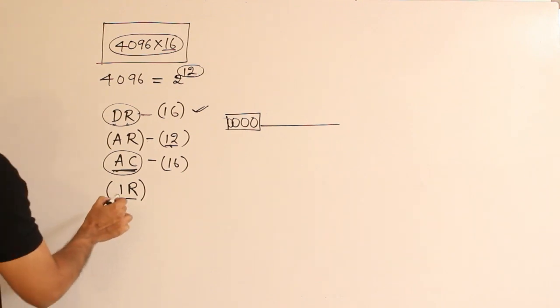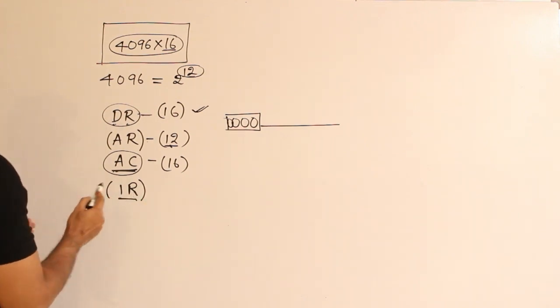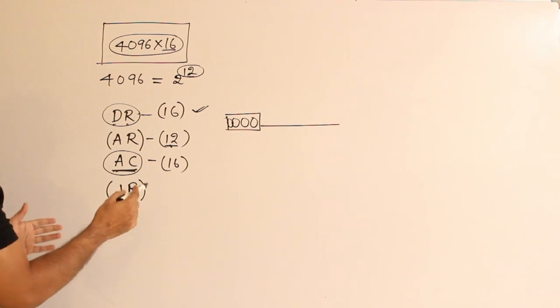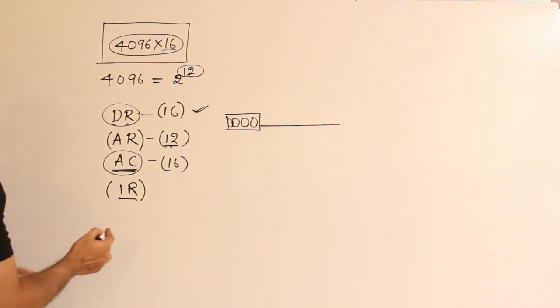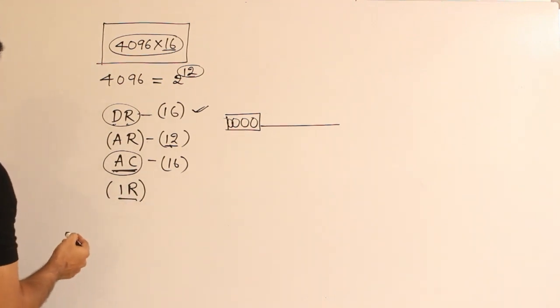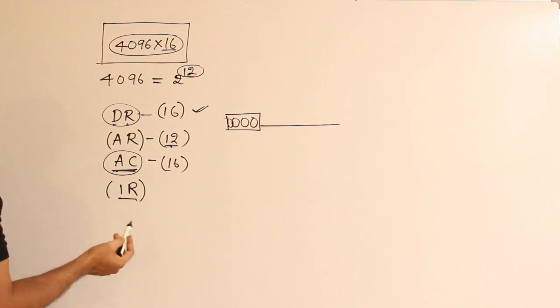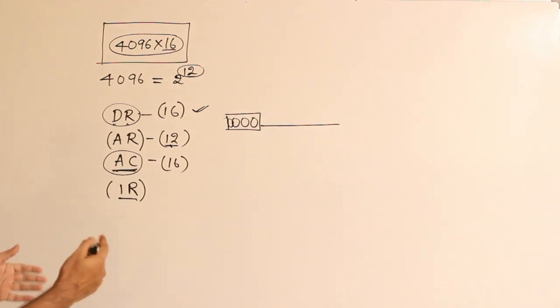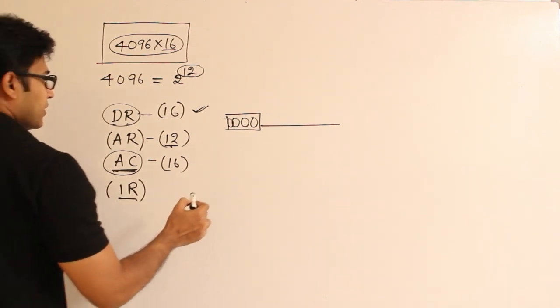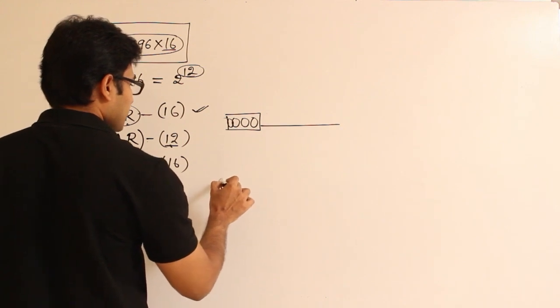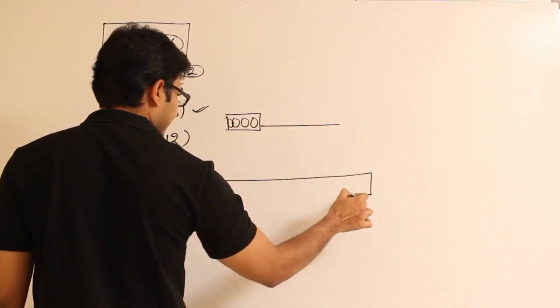So in order to do the decoding, we have to store it in a register, and that register will be connected to a decoder directly, which will say what this particular instruction is doing. The size of this register should be equal to the size of the instruction, or at least equal to the size of the maximum instruction that can be present in the computer. So in this case, let us assume that we are using instructions of size 16 bits.